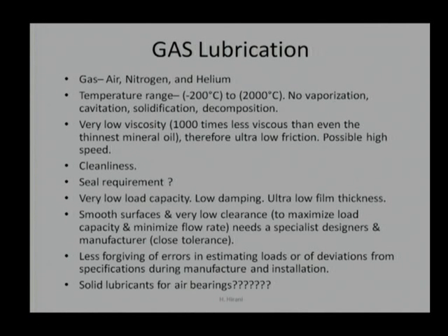So, gas lubrication requires extreme optimization with all calculation of unevenness, or we say that in all situations it should be working, otherwise it will turn out to be an unstable situation. A slight change in the load, and the surfaces may collide against each other, and there will be high adhesion between surfaces, that will be problematic. That is why I say that it is less forgiving of errors in estimating the loads. If the load estimation is not proper, then there will be a problem.